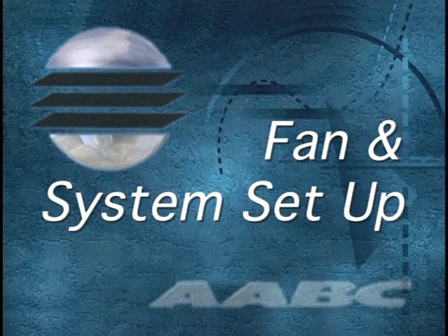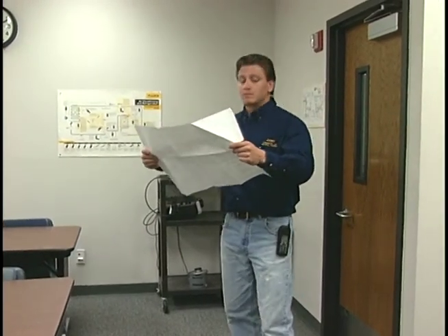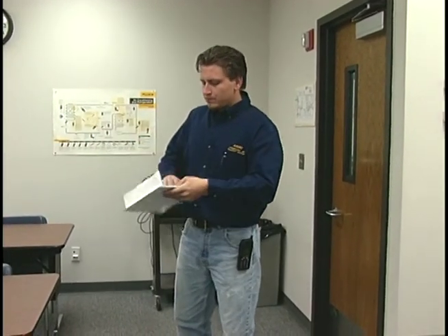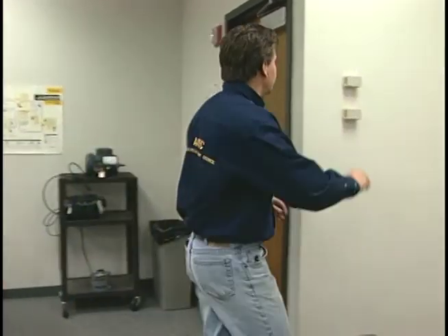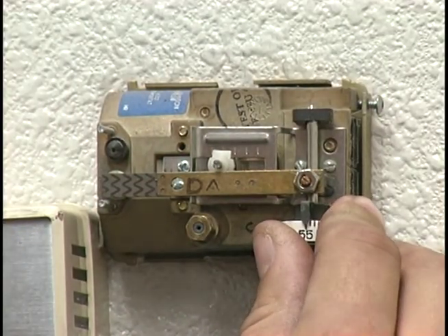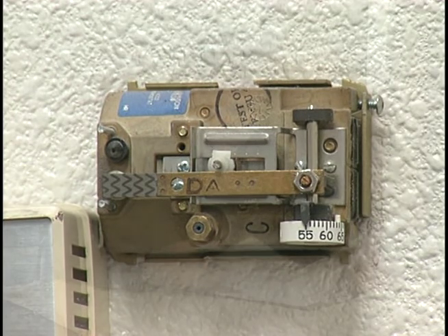Fan and system setup. In this video, you will learn basic air balancing procedures by going through the balance of a single-zone air conditioning system. Single zone is a control term meaning that there is only one thermostat in the conditioned space to control the heating or cooling for that space.